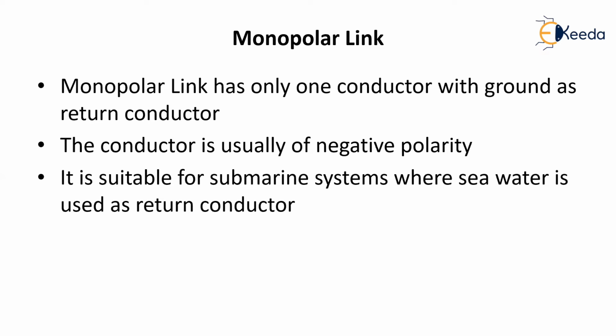Mono refers to single, polar refers to pole. So single pole link. Monopolar link has only one conductor with ground as return conductor. The conductor is usually of negative polarity. It is suitable for submarine systems where seawater is used as a return conductor.